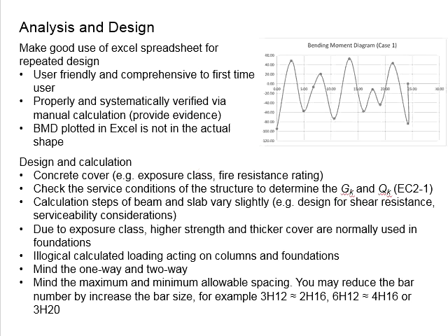As for the concrete cover for the foundations, especially when there is direct contact with the soil, it will depend on the exposure class as well as the nature of the soil, whether there is the existence of groundwater, whether the soil is highly rich in minerals, and so on and so forth. Normally the concrete cover will be thicker as compared to the other structural elements.